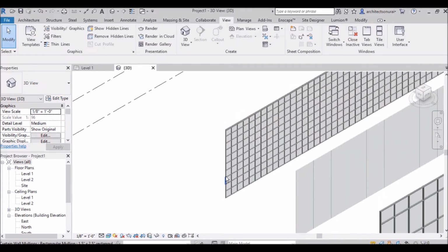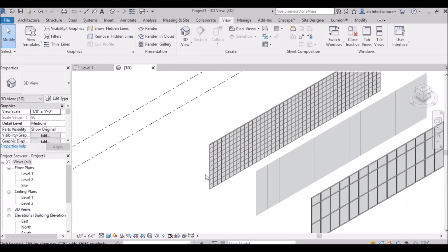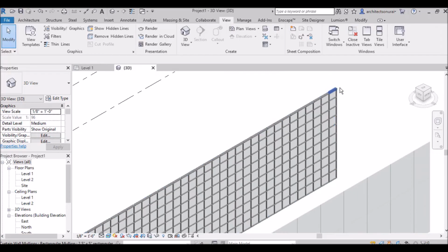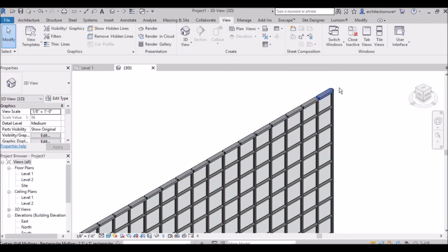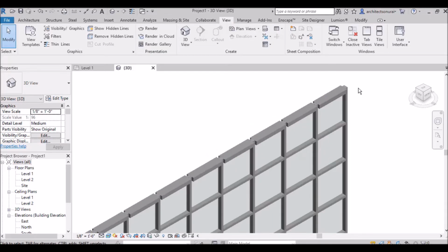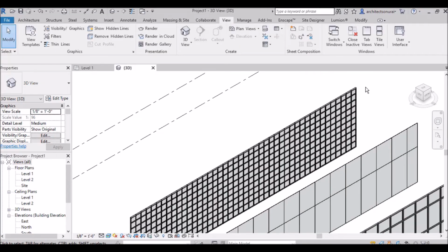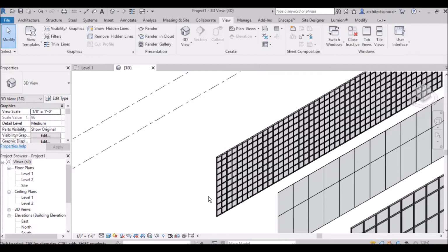These are placed, these all are border 1, border 2, which you have seen in vertical and horizontal mullion. So if you do not apply border, then this outer boundary of curtain wall will not be shown, it will be shown as glass. So now you have seen how we have easily edited the curtain wall here.